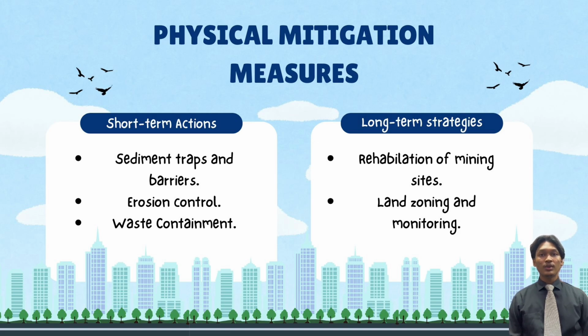For the short term, we can install sediment traps and barriers. Installing silt fences and sedimentation ponds prevents bauxite-laden runoff from contaminating water bodies. Using geotextile mats and cover crops stabilizes exposed soil for erosion control. For water containment, we can secure impermeable tailing ponds to prevent groundwater contamination.